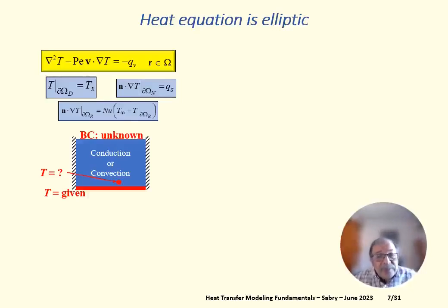In fact, if the temperature at the top wall was, for instance, 0 degrees centigrade, then the temperature will decrease gradually from 100 to 0, and the point I'm asking for might be at 98 degrees or something like that. But if the temperature on the top wall that I don't know was 200, for instance, then the temperature will increase gradually from 100 to 200, and the temperature at the point I'm asking for would be maybe 102 degrees centigrade, something like that.